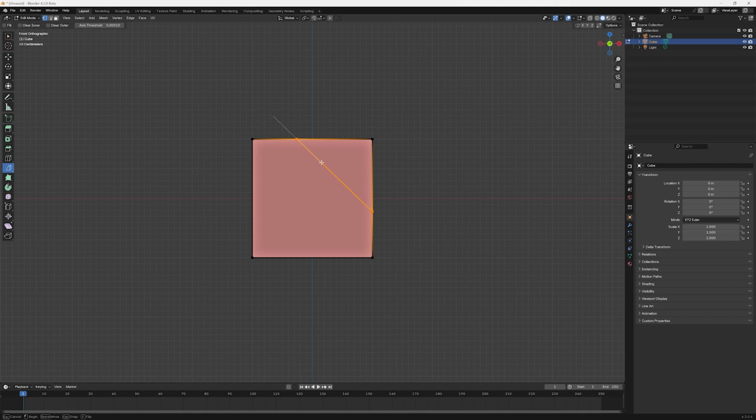When we release the left mouse button, the Bisect gizmo will appear with its center at the cutting plane's pivot point. The arrowed line indicates the direction of the cutting plane's face normal. Using the gizmo, we can make a few adjustments to the cut we've just created. Dragging on the yellow arrowhead will move the cuts and the pivot. As we move the mouse pointer close to the gizmo's circle, it will change from blue to white. This is an indication that we can now drag on the circle to rotate the cutting plane.